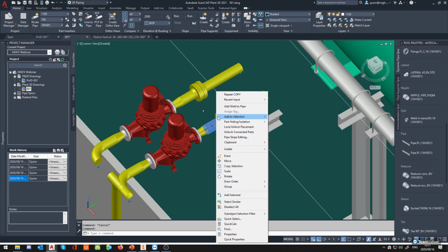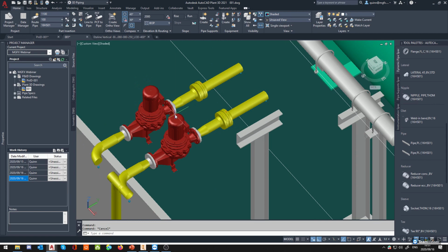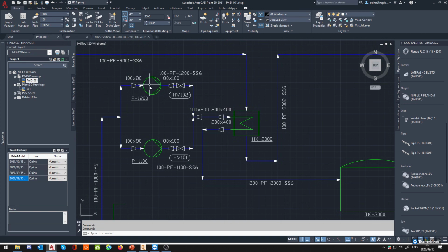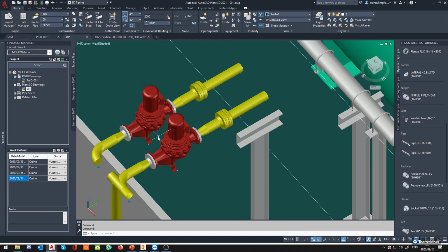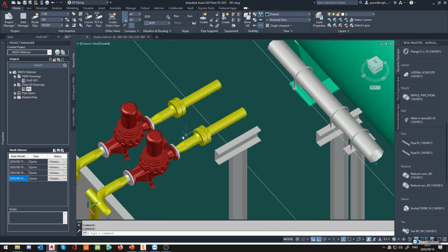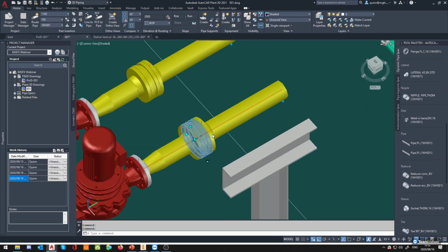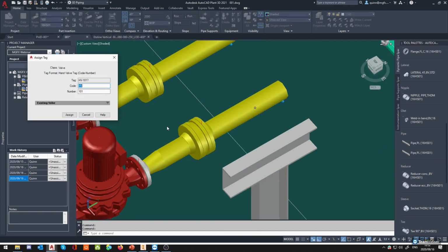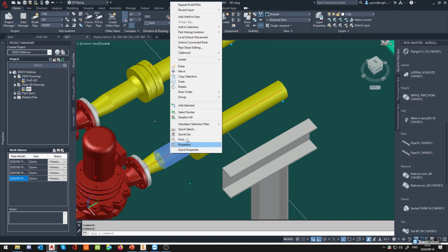But what this means though is that if I'm now copying items across, like think about this pump arrangement that you would have. In fact, I do have it over here, where you'll normally have a standby pump, so your main running pump and your standby. So this would be a normal type of pump arrangement. Of course, obviously you'd probably have a non-return on the one side, but that's part and parcel of course. So you could do the whole one side and then mirror it, or bring it around, then mirror it, depending on what you want to do, and only have to draw one item and then just fix up things like your valve, your actual labels. Most of it's already there, and it just makes it a little bit easier because then you know what you have to change.